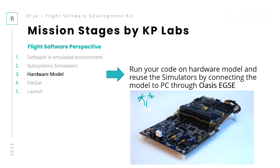Okay, so that's an important part. There are no flags to switch if you are switching between engineering and flight software. If your engineering model is close enough to the flight one, and by close enough I mean it only has to have the same memory layout and the same peripherals, then you can use the same code. You don't have to, for example, disable EPS monitoring because you have no EPS. Well, you have the simulator right now. You can use this.